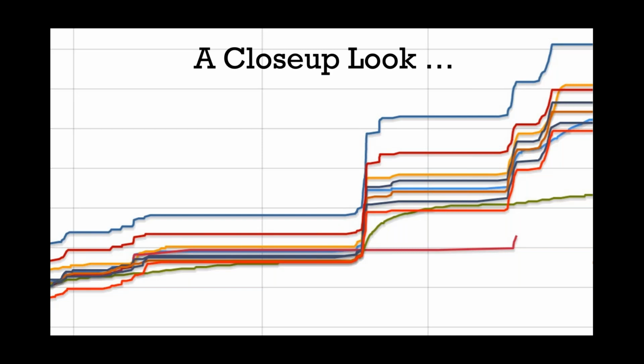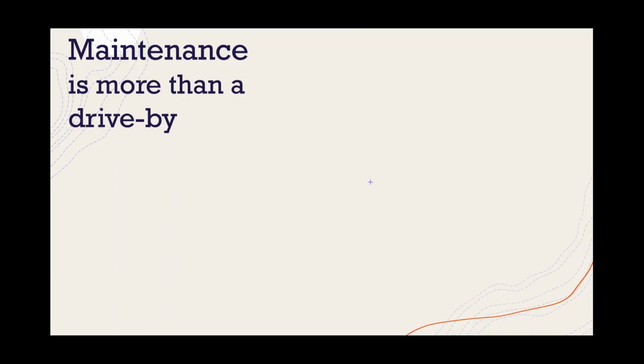There's just a number of different things. I could look at that graph right there and see at least 6 or 7 indicators of a problem at a rain gauge before you ever get there. You need to go to these sites already with an understanding of what might be wrong there. And this is the purpose of these data analyses.